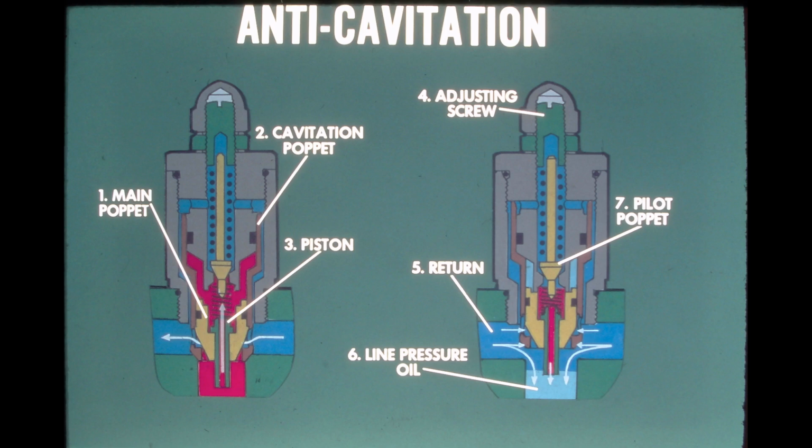The relief pressure setting can be changed by adjusting the tension on the pilot poppet spring. The anti-cavitation valve has no provision for adjustment. This program continues on tape 2.